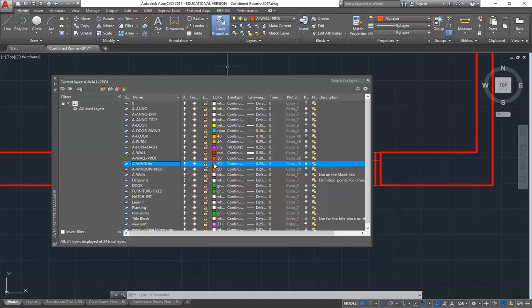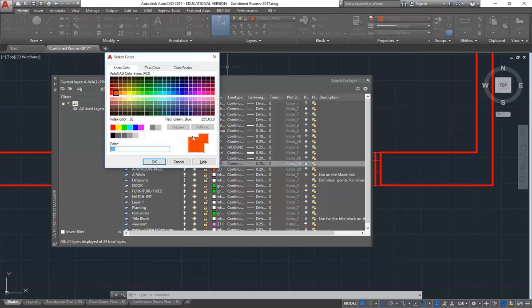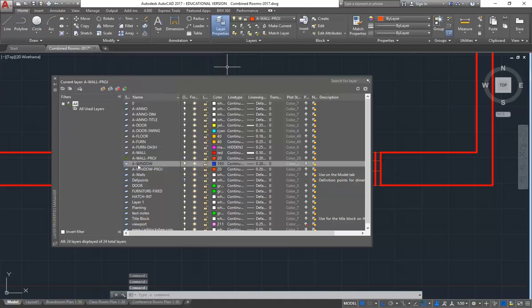And I don't know, when you were doing your hand drawing, this is something you're thinking about, how to get the different parts of the things you've been drawing broken up so that they've got the right line weights? Oh, okay, yeah. Because you might be taught a bit differently. The way I was taught from first year really is that everything that's cut should be heavier, and things that aren't cut or are below the cut plane should be lighter.